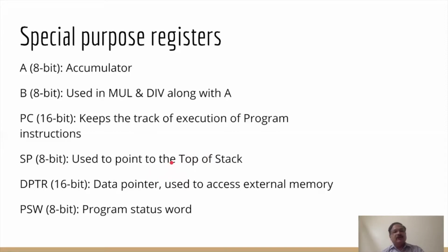Whenever you feel that the number of registers is less and you want to use the registers in your program again, what you can do is save the current contents of the registers onto the stack temporarily, use the same registers again for your manipulation, and whenever your work is finished, you can pop that from the stack and the original contents will be retrieved back in those registers. So the stack pointer always points to the top of the stack.